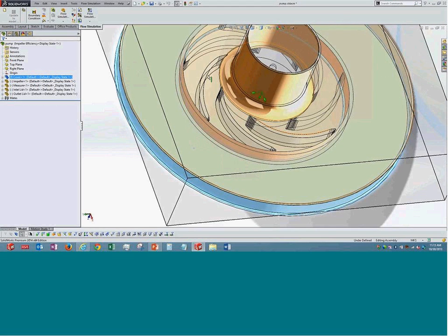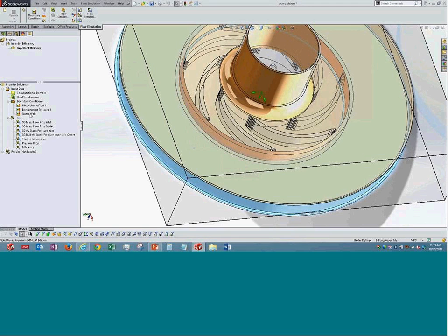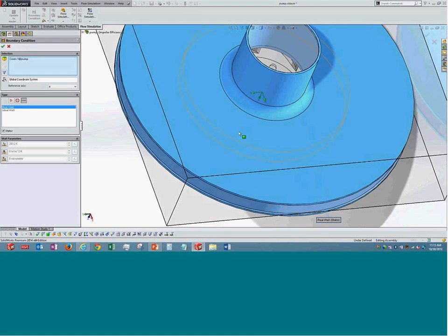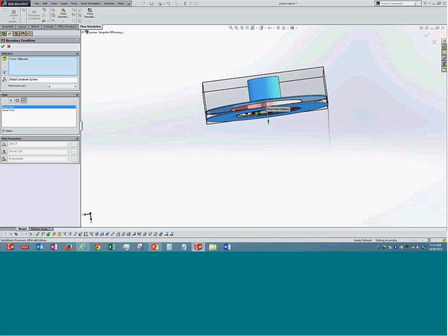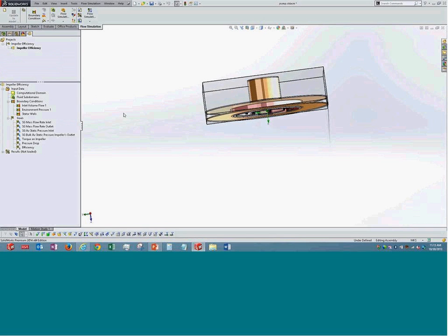One of the important things which I mentioned in one of the questions before was torque. So here we have selected torque as one of the calculation outputs. It is going to tell you the torque that comes on because of the flow or the forces that are coming on all these fan blades. Basically, it is going to converge on the torque and give us accurate values. It is also finding the pressure drop from inlet to outlet, and finally efficiency, which is very important.